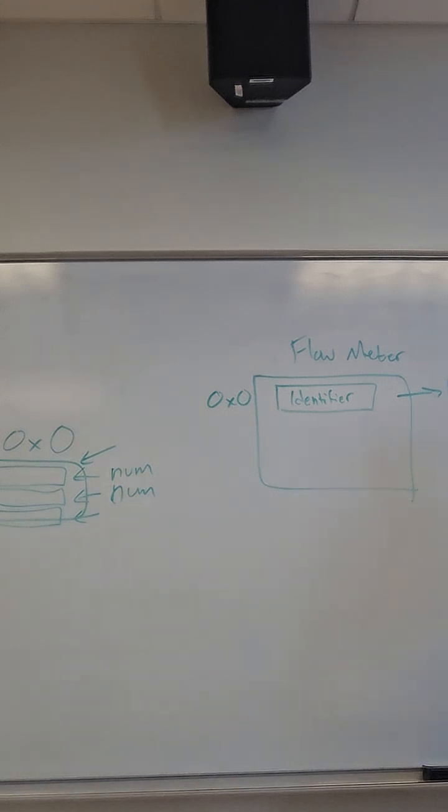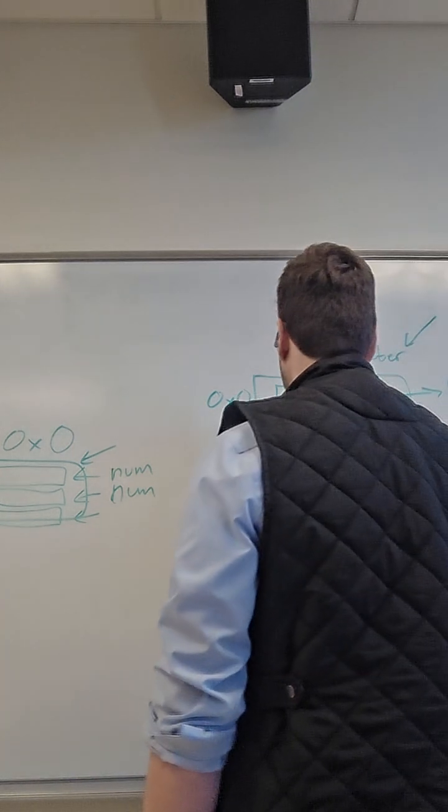And this could be a good sanity check that when I first talk to this device, I go, hey, flow meter 1, flow meter 2, give me information that's in your first register, that's in register 0. And if I get 0xAF, I know I'm talking to the right device. If I get anything else, then something else is up. I'm talking to the wrong device, there's a networking issue, whatever. And then it continues from there.